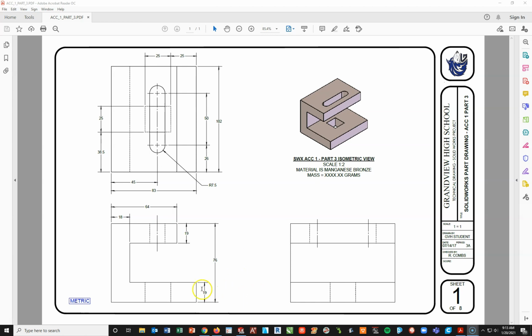In this case, the easiest thing I see is to start from the front plane and draw basically this C shape. We'll get all that dimensioned, using all the dimensions we see in this drawing, and get this general shape right here, this little C. Once we get this shape, we will use our extrusion tool in SolidWorks and extrude it a distance of, in this case, 102 millimeters.